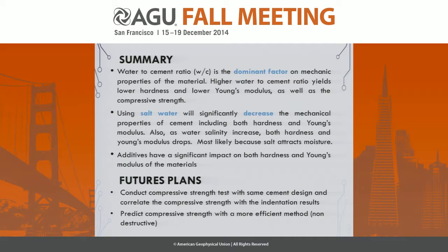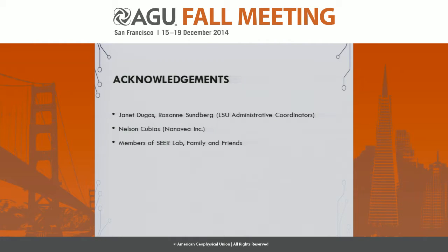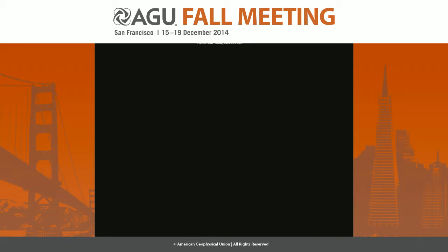Our future plan is to conduct the compressive strength test with the same cement design and correlate the compressive strength with the indentation results. Hopefully, we can predict the compressive strength with a more efficient method. Acknowledgements. That's it. Thank you.